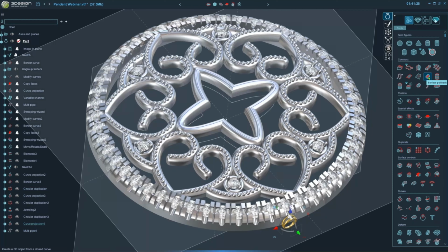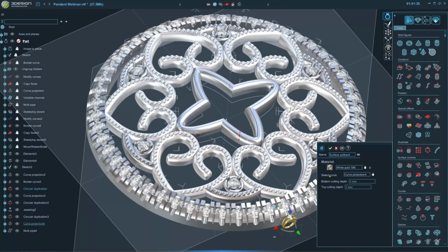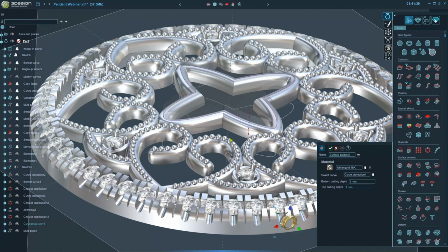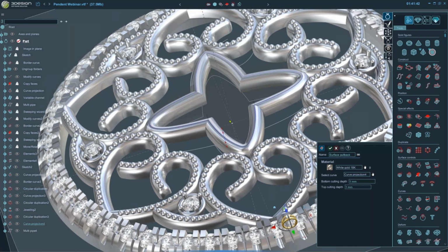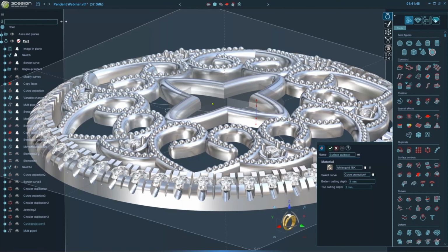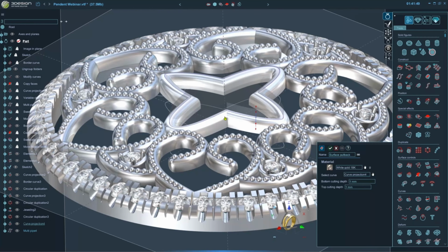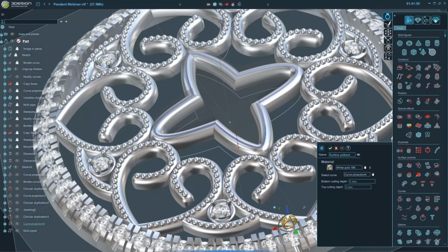Basically going to use the surface itself to create the top and bottom of this and then create a solid from it. So if we preview it here, you see that it's basically going to pull back that surface in both directions, 1 millimeter by default. That's definitely too much. And then extrude based on the surface direction, the outside, and that's going to put it all together. This doesn't work on really complicated detailed shapes.